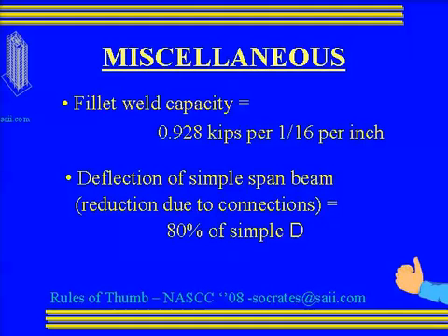Another simple fact, but often ignored, and I had a whole paper about this about 10 years ago to prove that this is the case, and several others have followed since then, is that the deflection of a simple beam is usually 80% of what you calculate because of the connections providing some rotational capacity, even simple bolted connections.